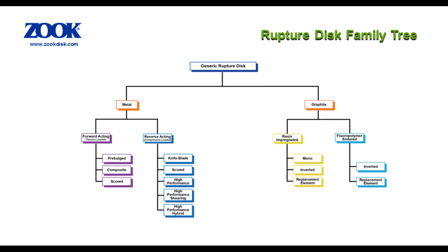Resin impregnation is the first and most common process used. Various resins have been used over the years, but typically are either phenolic or furane-based. Through a process that includes pressure, vacuum, and temperature curing cycles, the graphite pores are filled with a cured resin that renders the graphite material impervious and suitable to use as a graphite rupture disk. Resin-impregnated graphite provides good corrosion resistance, inert material with non-ion contamination, temperature stability, and predictable results.